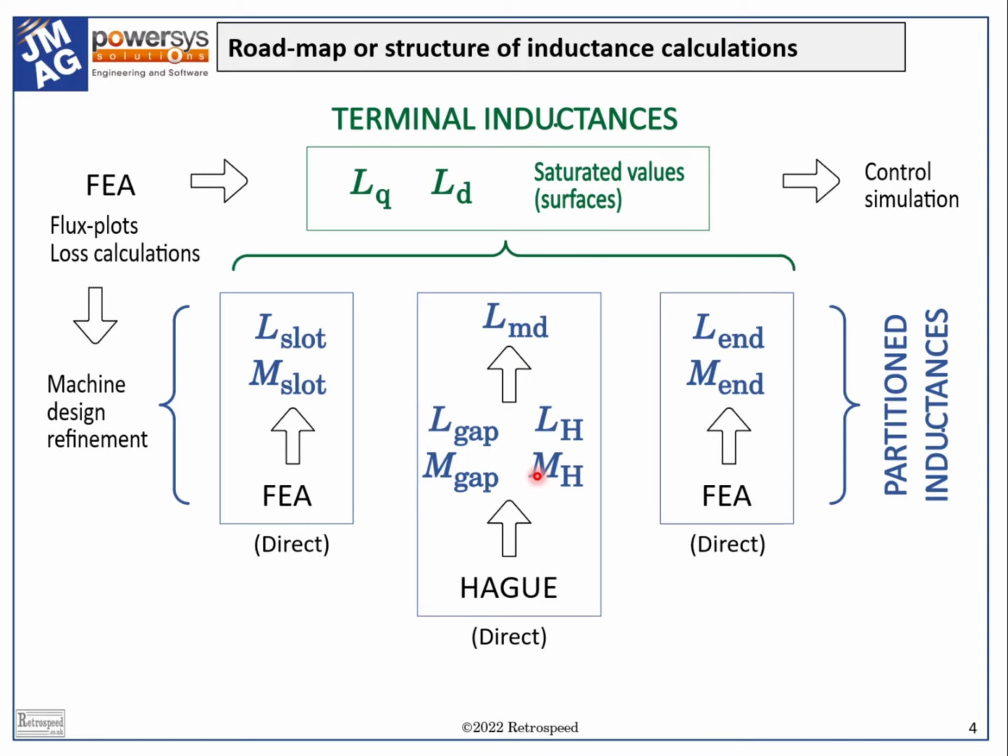The same coefficients that arise in the inductance analysis, the harmonic distribution and pitch factors, and sometimes the skew factor, are the same factors that appear in the analysis of the EMF waveform, and they also have a bearing on the cogging torque. It's impossible to make a satisfactory winding design without a proper calculation of these winding factors.